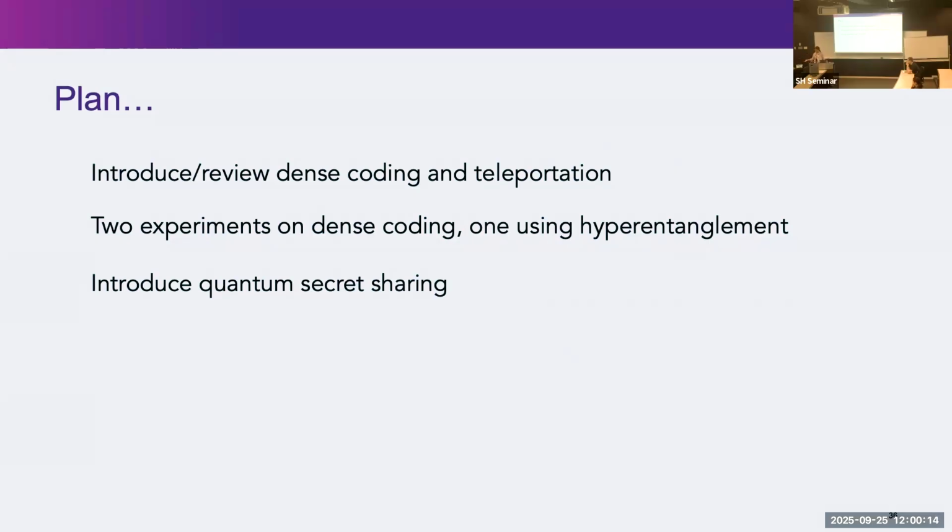It's a huge beast. I call them our moody EBLs because sometimes they work well, sometimes they don't work well. But anyway, so they made a database of all the fabrication runs from their EBL, so they get a better idea of their fabrication characteristics, and then they put that into the inverse design software that they have. They don't use SPINS. I think they have their own package. We use the Stanford one from Jelena Vuckovic's group.